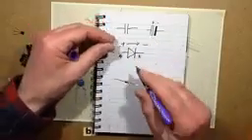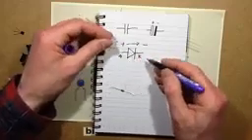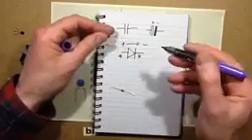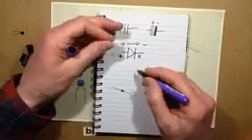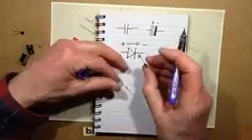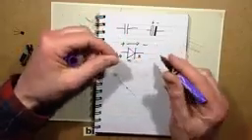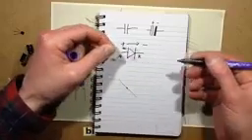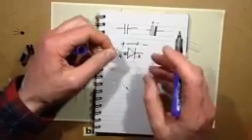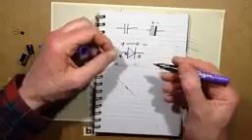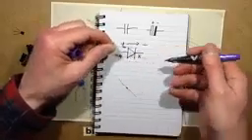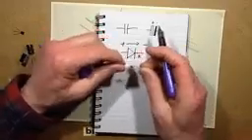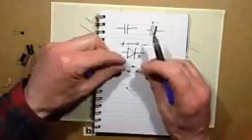And the other factor is the peak inverse voltage. That's the voltage it will block coming in the wrong direction. So this one is a 1N4007, it's rated 1000 volts. So that means that it will block 1000 volts going the wrong direction. But if you were to exceed that dramatically, it will avalanche and it will start conducting in the opposite direction. So you have to choose the correct diode for the job.